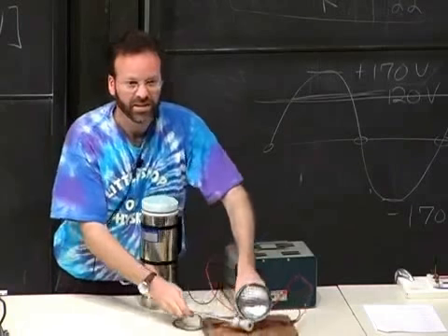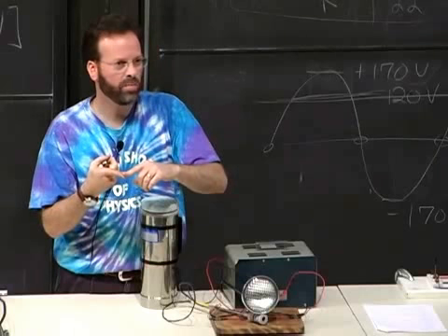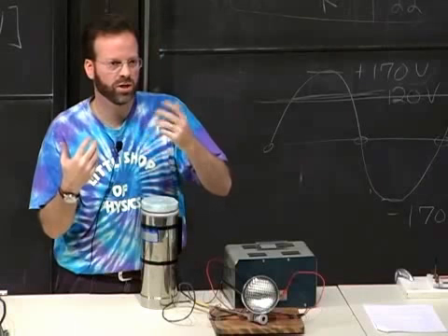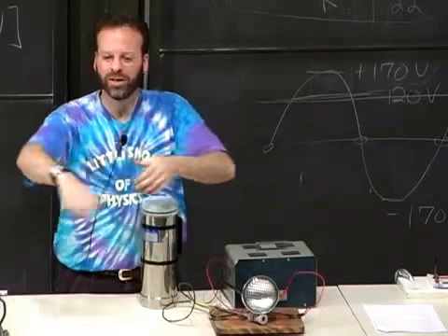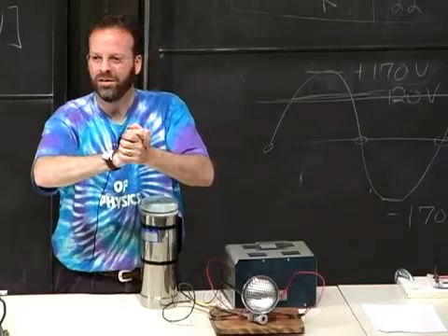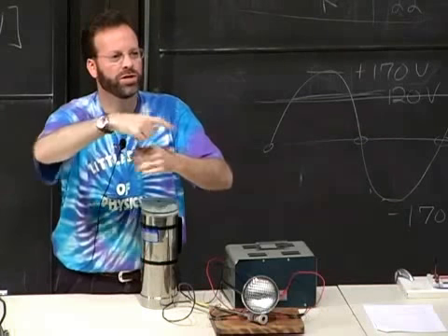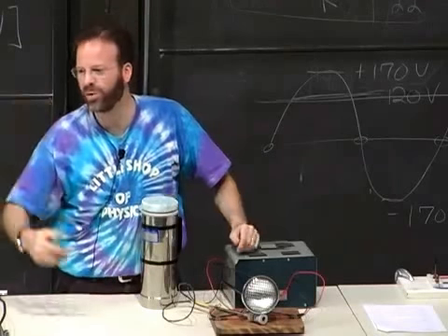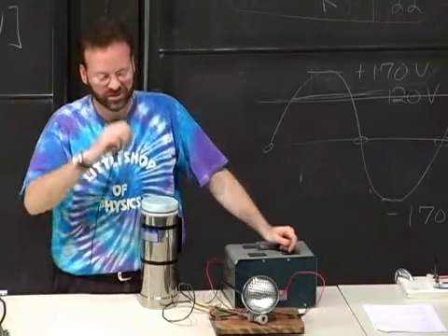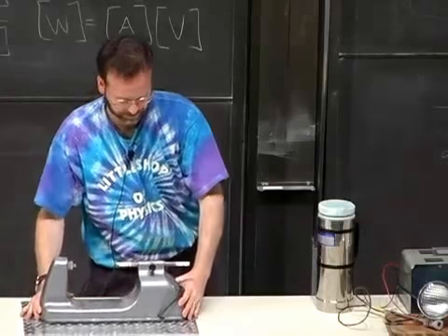Good questions. So again, resistance can be affected by size, shape, length, skinniness, what it's made out of, and the temperature. All can affect. If we were sweaty and we did that circuit up here, water's a better conductor. So the total resistance in the series circuit would drop, more current would flow, and it would hurt us more. Yeah. I think it's kind of counterintuitive to me that chilling the metal would increase its resistance.